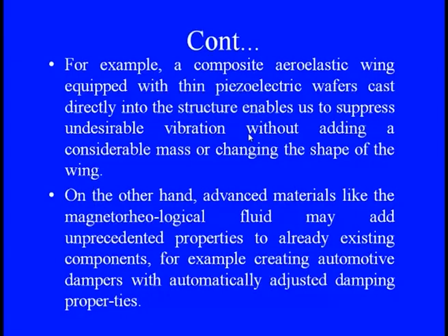Like a composite aeroelastic wing equipped with thin piezoelectric wafers, cast directly to the structure, can straightaway suppress the undesirable vibration without adding any seismic or added mass, without changing the shape of the entire wing, or adding any damper or spring elements.